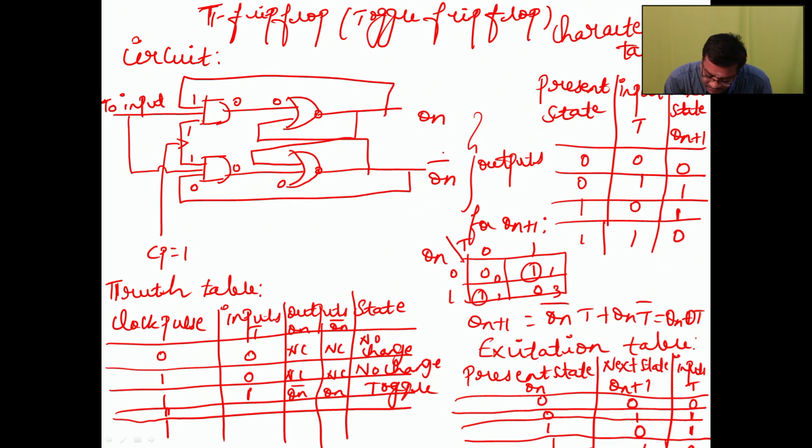So automatically when you consider this, we will get no change conditions. Next I am giving the input 1 here. Input is 1, we will get the output 1. Here the output is 0. Here 1, the output is 0. When 1 is the input, automatically the output will be 0 for the NOR gate. So here 1. This 0 will access and feedback, so we will get 1.